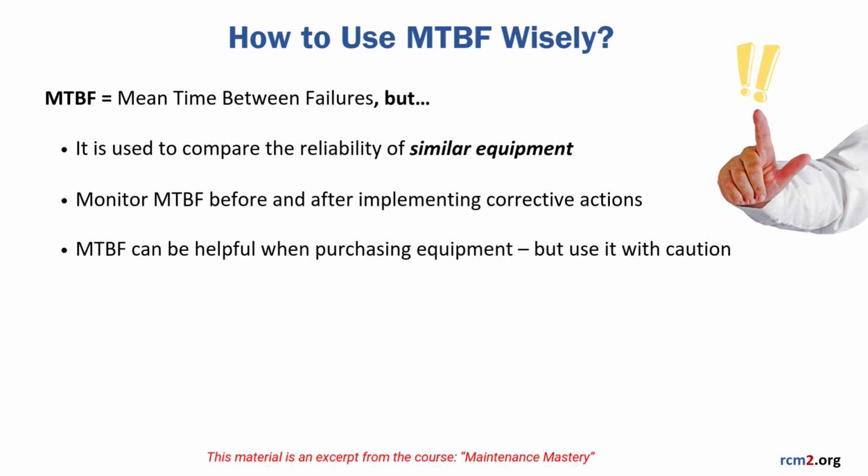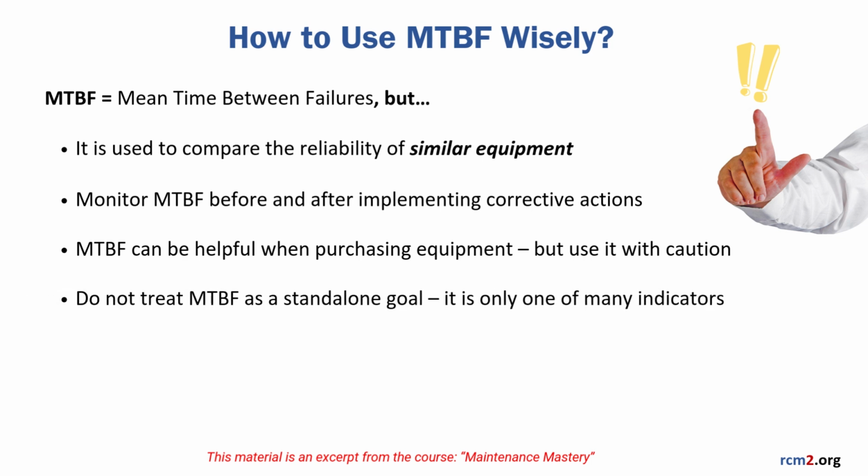It can also assist in selecting new equipment, but only if we compare similar machines and know how the manufacturer has calculated the MTBF. However, never treat MTBF as a goal in itself. It is only a supporting tool for decision-making, not an oracle. Misunderstanding or misusing MTBF can lead to serious costs and poor decisions.